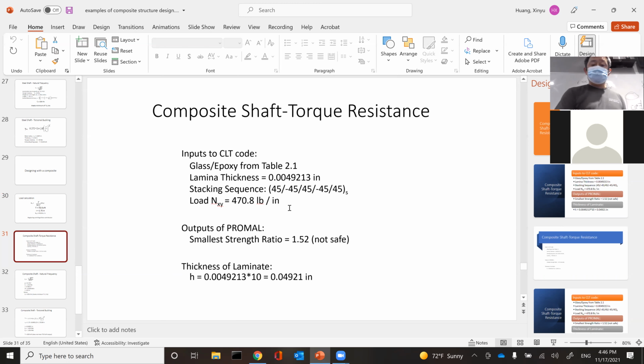You see in this design, a 10-layer symmetric layup is proposed. You can see it started with a symmetric layup, which is preferred. If you can use a symmetric layup, it's better than an unsymmetric layup. You have less coupling, unless coupling is what you desire. Most people don't desire dealing with the couplings. And then you can see most of the fiber is in the plus minus 45 directions, which is the principal direction for the torsion load.